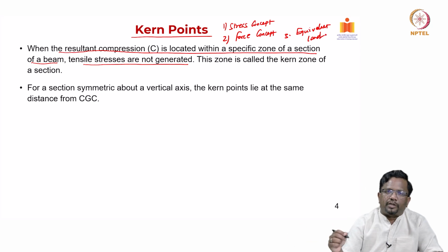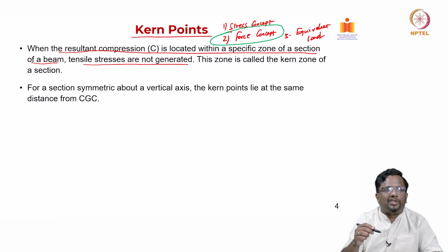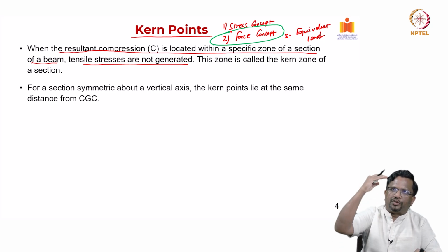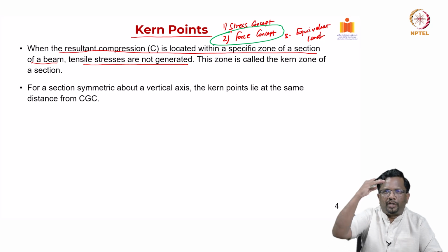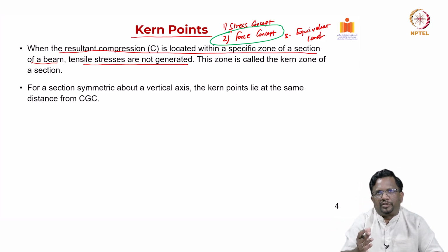In that, we said in pre-stress system, the most common one used in design is the force concept or the C line concept, C method, right. So, the system is going to be assumed to be in elastic state, that means no crack, and depending upon the location of your compression force, we just apply this compression force as an external force and then we do the analysis that we have discussed in the previous chapter.